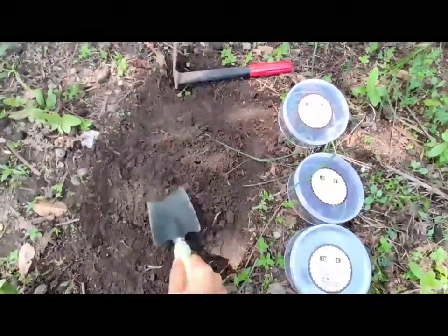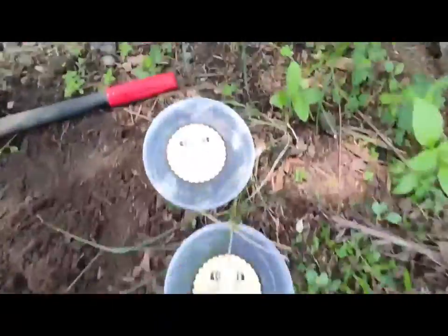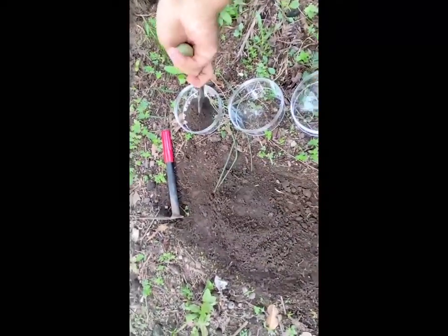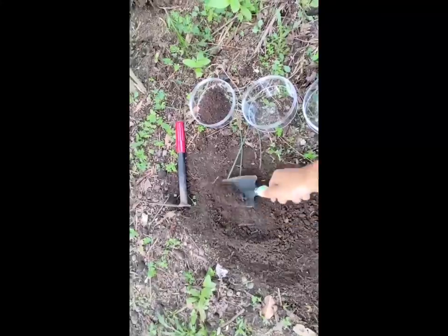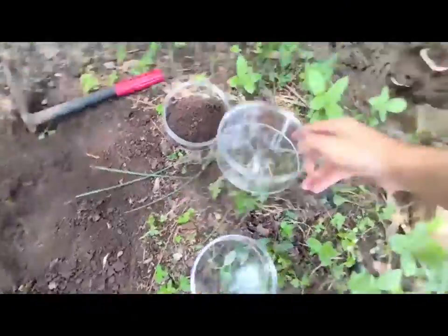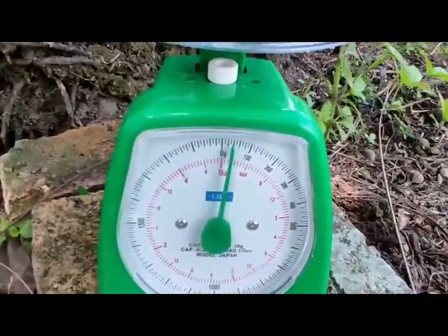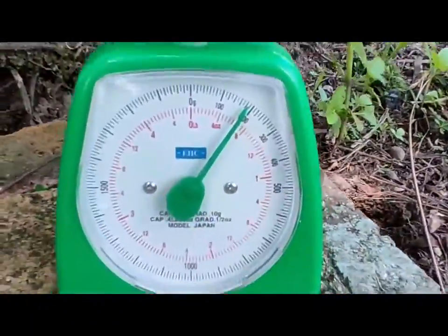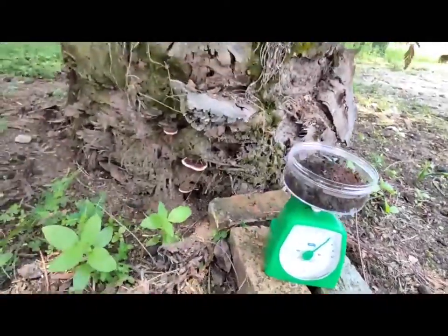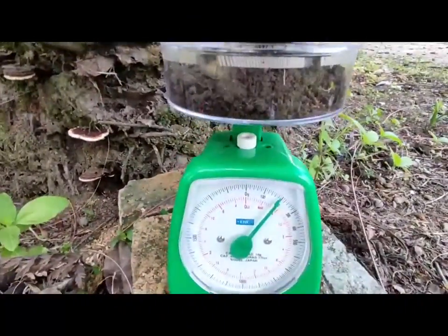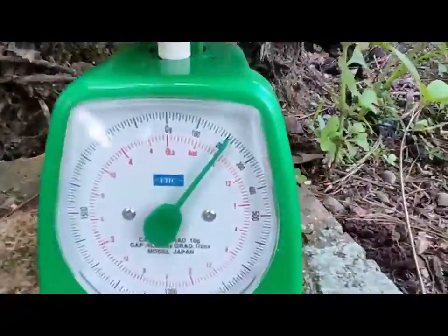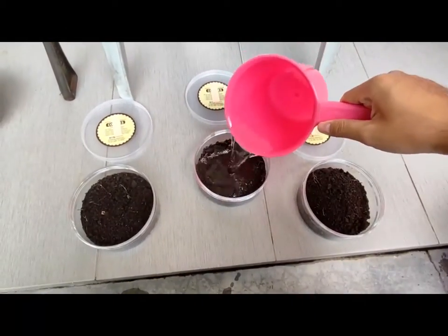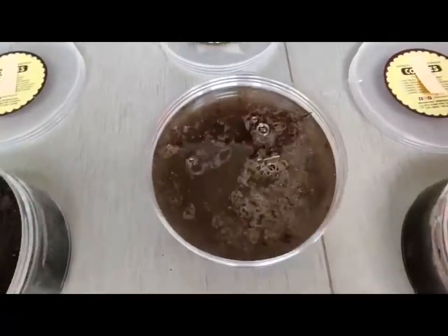For the procedure, I try to replicate the laboratory standard procedure. Firstly, we will record the mass of the container, and then the mass of the container with our soil sample, and then we will fill the container with water and make sure there is no bubble, and then we will record the mass of the container with wet soil, and lastly we will record the mass of the container fully filled with water.